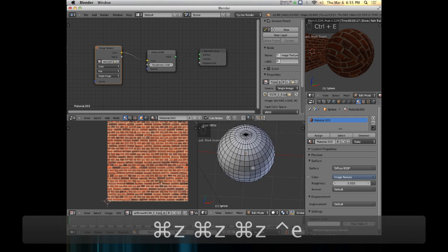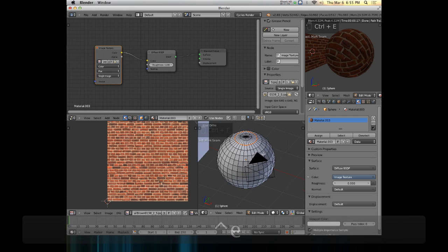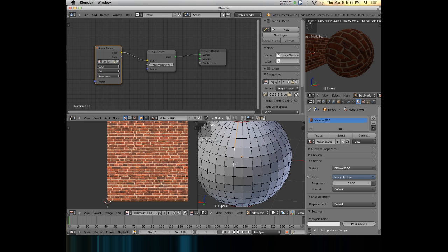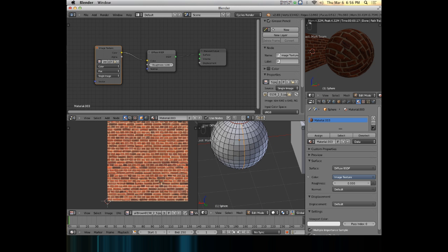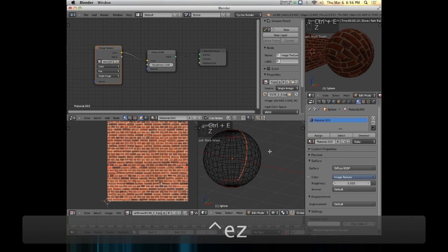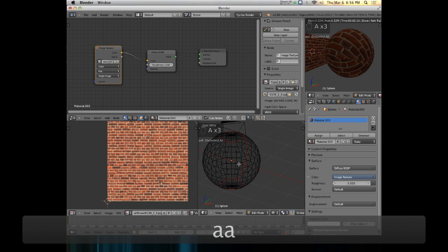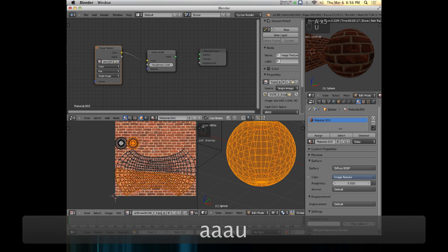So I've got one on the top. Oh, now I have one on the top and the bottom. And then I'm going to go around to the back side of the sphere that I'm not going to see on camera, and I will select this edge loop here. Or, well, this edge, not the whole loop. Okay, so I've got this edge selected between the two seams that I already marked, and I will mark that seam. Okay, so you can see these are the seams that I have marked for my sphere. I'll select everything and hit U and unwrap. Okay. And this is how the sphere unwraps.